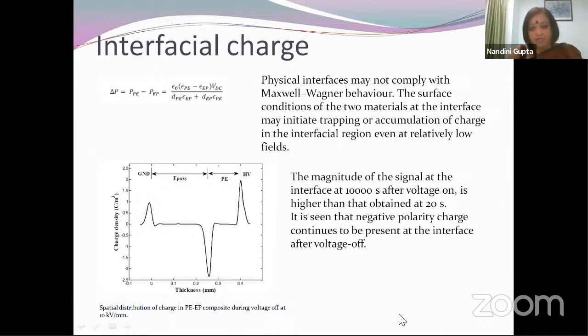Afterwards, this was part of Dr. Qasim's work. When he worked with functional materials, he had the same problem, and he was able to solve it very nicely by using hot compression. He'll talk more about this. We took the samples and bonded them together, and after that, we applied temperature and compressive forces. That had to be fine-tuned. We had to figure out what temperatures to use and what compression to use. It cannot be more, it cannot be less.